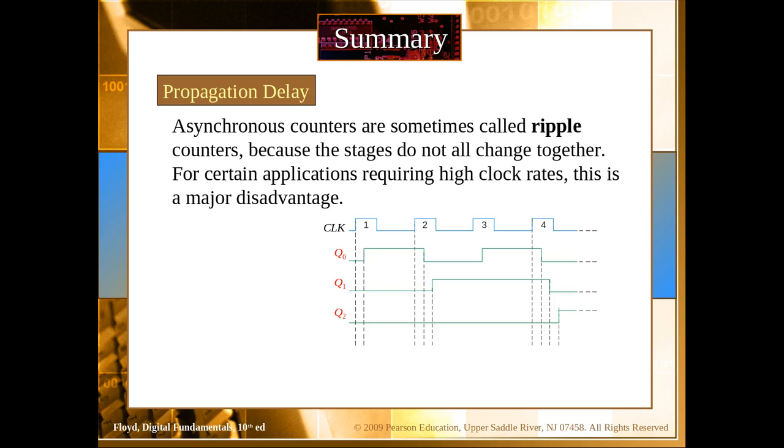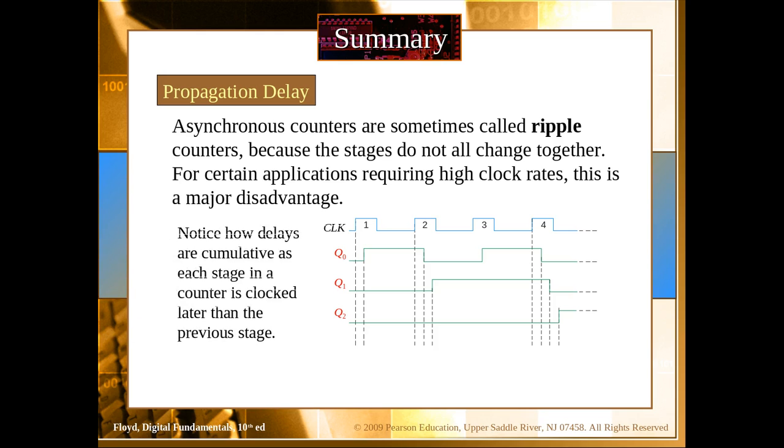the time is not larger than the time period of the clock, so that the 2 pulses of the clock are not mixed together. This is a major disadvantage of an asynchronous counter, but we can also have a synchronous counter, which you would see in the subsequent slides, where we would avoid this propagation delay problem.